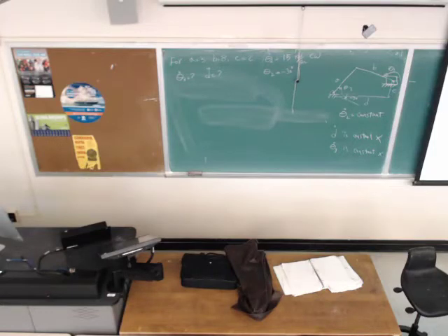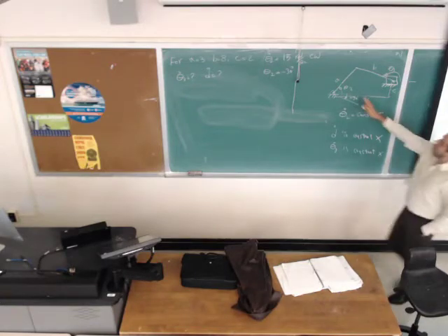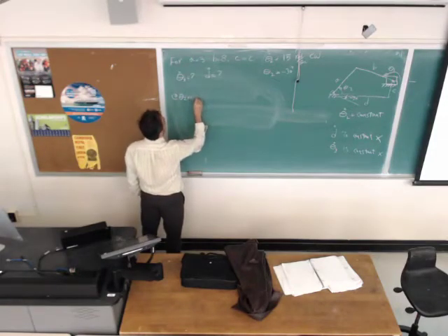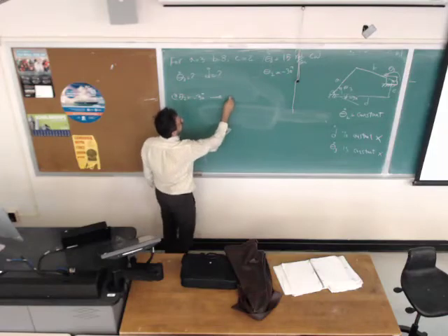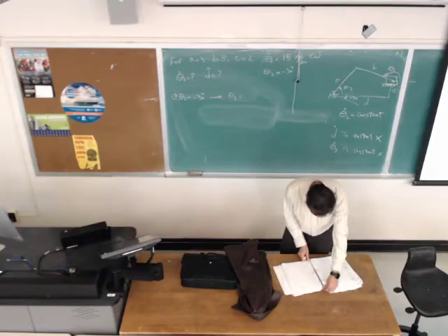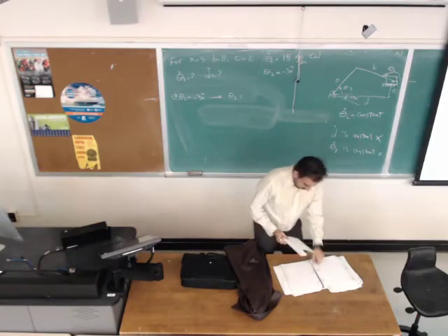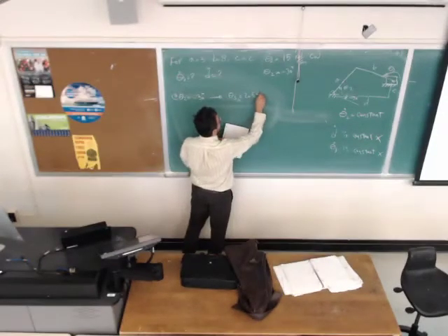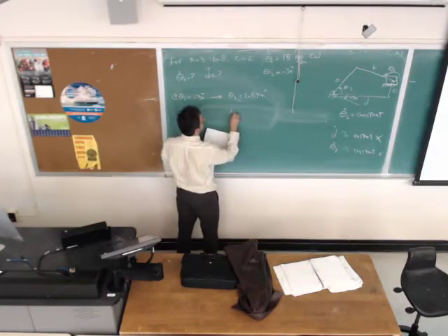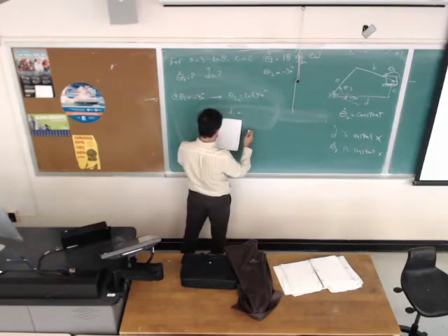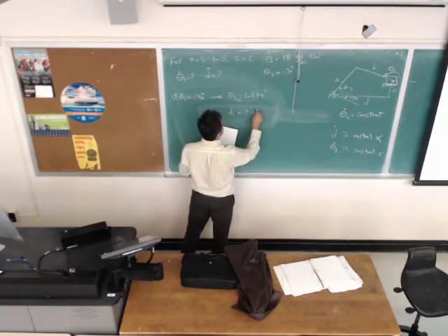So in velocity analysis, we should perform displacement analysis first. At theta 2 equals negative 30 degree, we will get two modes. Theta 3 for the first mode is 205.94 degree, and D for the first mode is 9.8 inch.